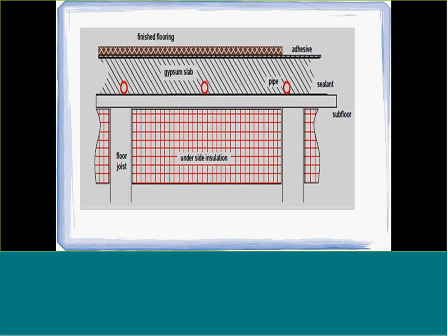This is, did I miss a slide? No. This is an installation where we would be pouring over a wood floor, a wood subfloor, and we would attach the tubing directly to the subfloor, usually staple it or use a nailer to fasten it to the floor, and then they would come in with a gypsum overpour, the same type of product you use to level floors in large buildings. It's a slurry, so they bring it in with a hose and just pour it on the floor.